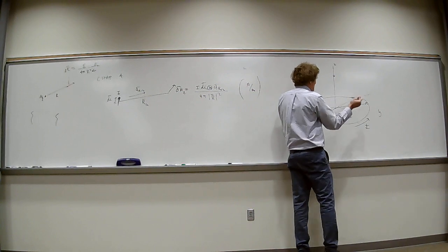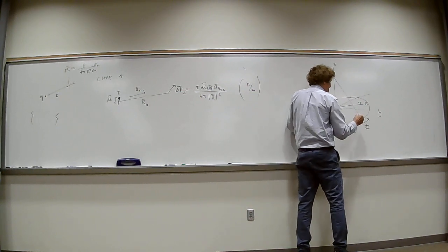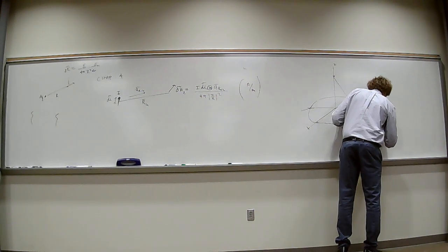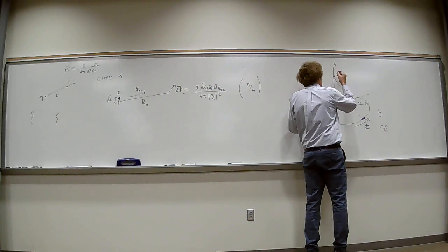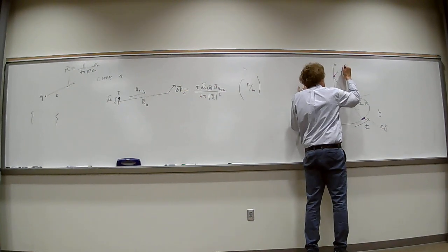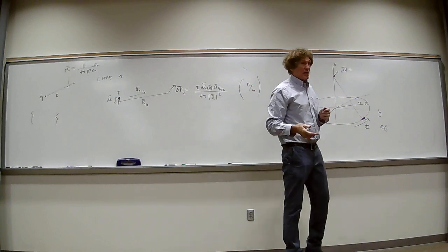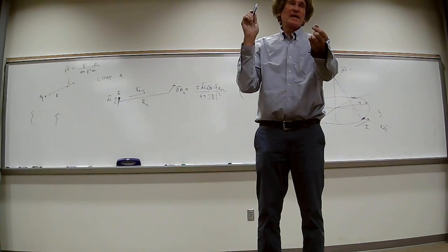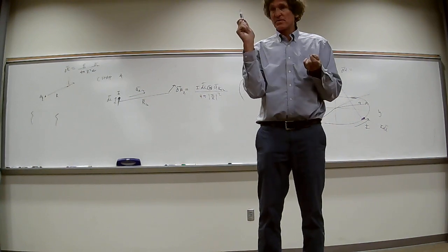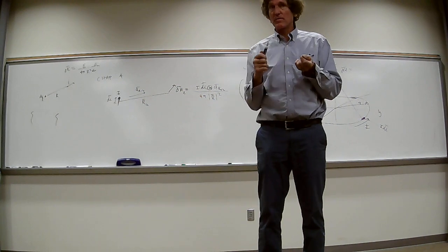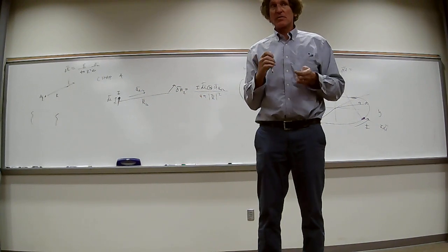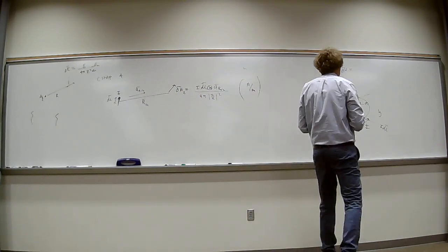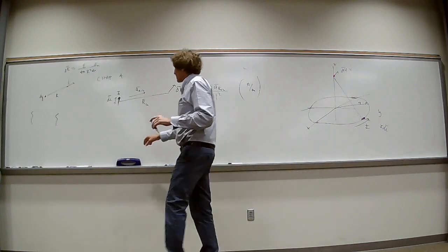That's what we want. So we come down here, and say I have a differential chunk of current here, call it I dl. And from that, I want to know what the differential H field is. And then I'm going to go ahead and integrate the differential H field, or integrate the effects of the total loop to get the total H field. Find the differential, then integrate over where the charge exists to get the total H field. Do you all follow me on that? Okay, so now we have to say what dH is, and I'll do that over here.